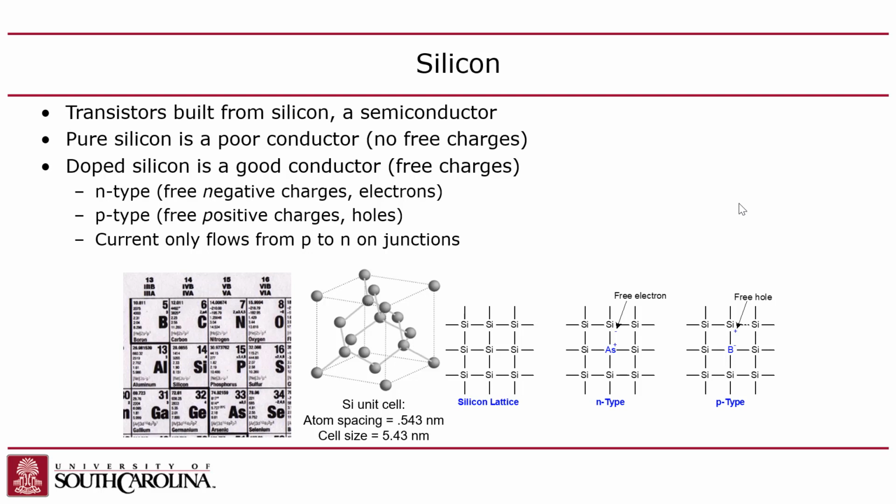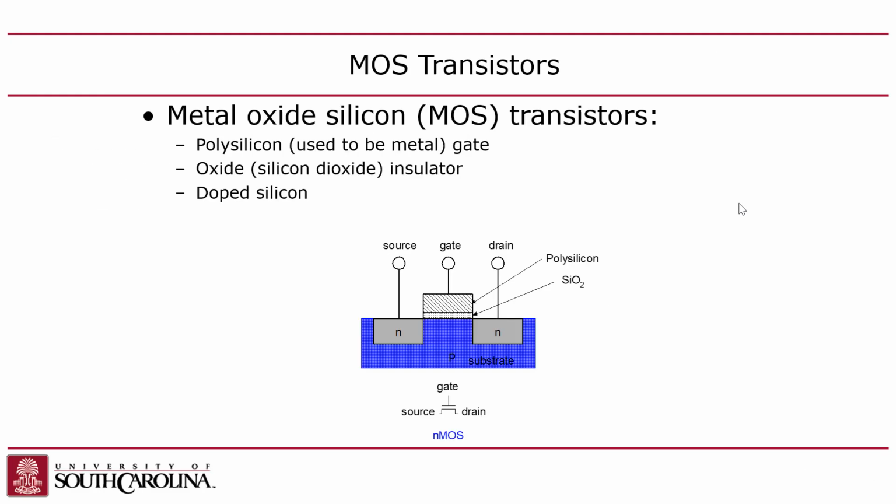How did they get in there? Unclear. They're contaminants, right? They're just in there. But the minority carriers don't play any part in the operation of a diode. So when it comes to diodes, it's just the majority carriers that make a difference. However, the minority carriers do come into play for a transistor. The way that you build a transistor is basically from diodes. One more thing I want to mention: a diode is just two pieces of silicon doped different ways, butt coupled together. That's how you make a diode, very simple.